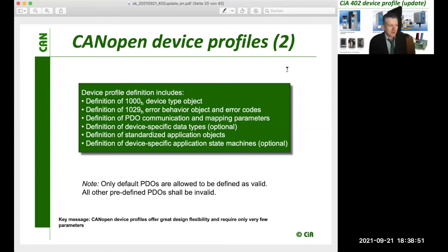From those, if you remember from CANopen 301, there is a range of indexes reserved for the application itself, from index 6000 to index 67FF hexadecimal. This is the application profile. Within this application profile, every CANopen application profile may have its own parameters for this specific kind of device. The same applies for drive profiles. So there you find only drive profile specific data.